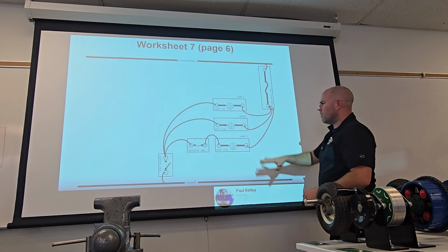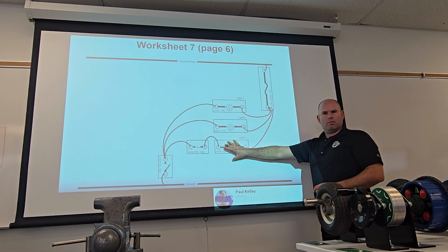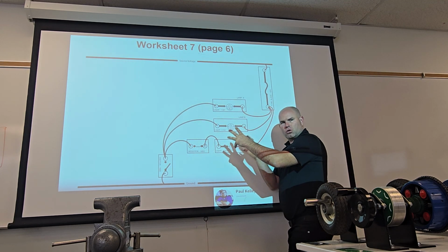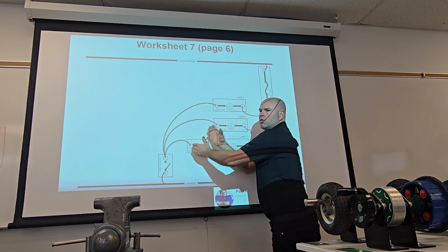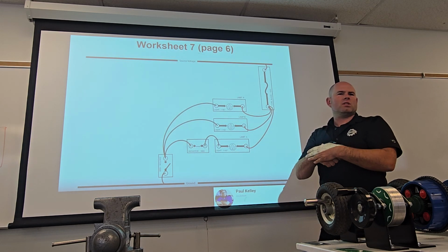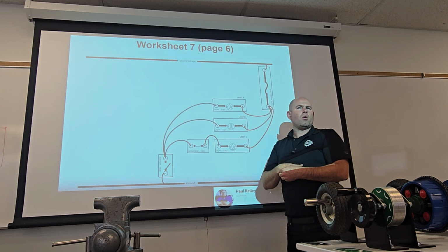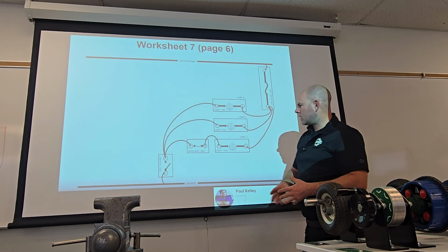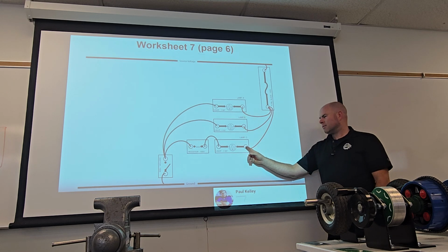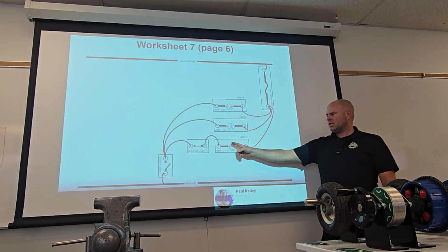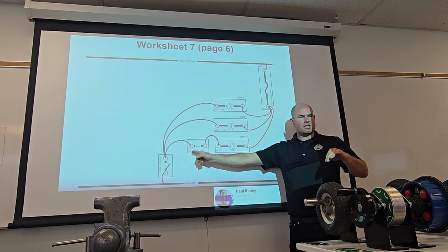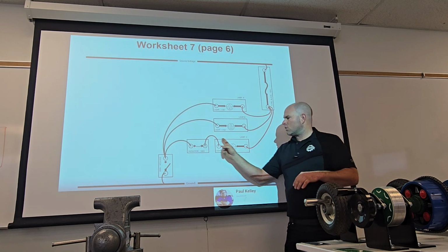Cool? Now, this one's going to be different, though, because this one, exactly, and so let's speak of it as if you do see the resistor, and then we're going to switch it to if the resistor was like a, not necessarily a component, but like a corrosion in the connector, okay? What you'd see here, would you agree that there should be 12 volts here? Okay. What should there be here? 0. There should be if there was no resistor,